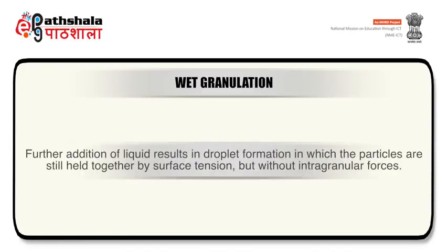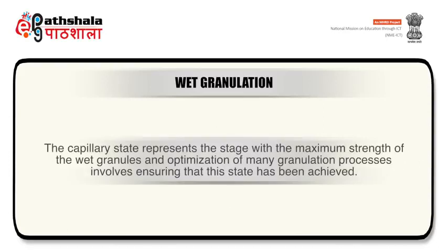Further addition of liquid results in droplet formation, and the particles are still held together by surface tension but without intragranular forces. The capillary state represents the stage with the maximum strength of the wet granules. Optimization of many granulation processes involves ensuring that this state has been achieved.